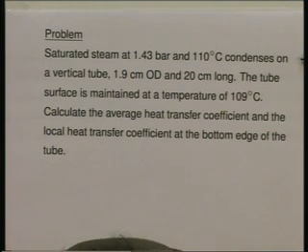Saturated steam at 1.43 bar and 110 degrees centigrade condenses on a vertical tube 1.9 centimeters OD and 20 centimeters long.